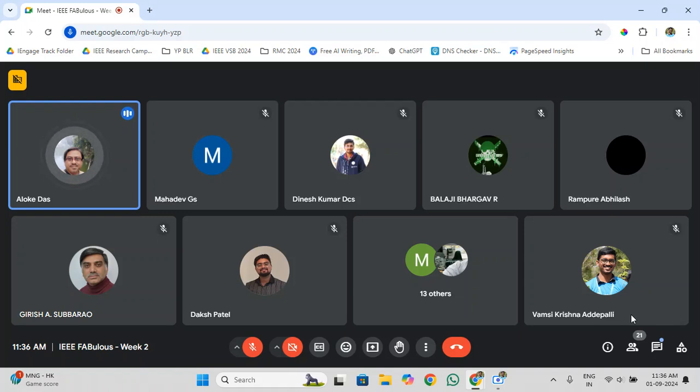And this is for a particular fab. If the fab changes, like from TSMC to GlobalFoundries, this will also change, but the test bench and SPI don't change. So I am expecting the design and test bench at bare minimum. But if anybody is interested, I can cover it separately and show them how to tape out end to end.